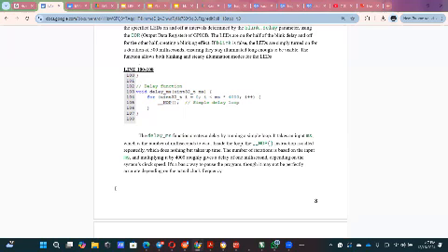The number of iterations is based on the input milliseconds multiplied by roughly 4,000, giving a delay of 1 millisecond, depending on the system clock speed. It is a basic way to pause the program, and it may not be perfectly accurate depending on the actual clock frequency.